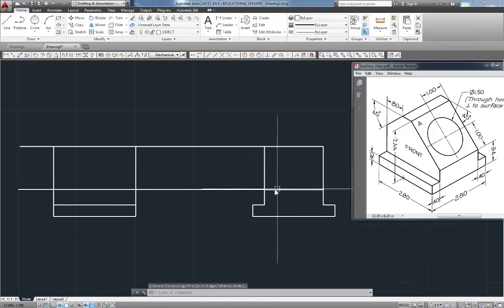And then this starts the slanted surface here, and it's at a 45, so I'm going to do a line. Straight up is 90 plus 45 is 135, so we're going to go angle 135.